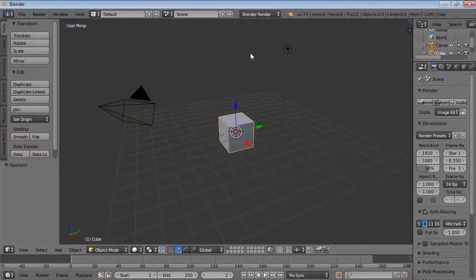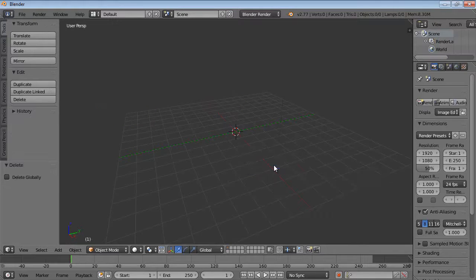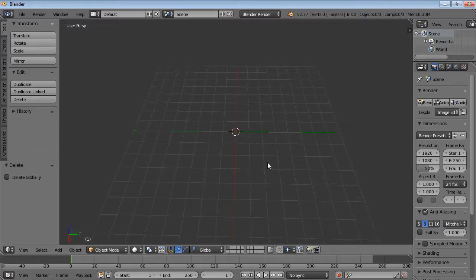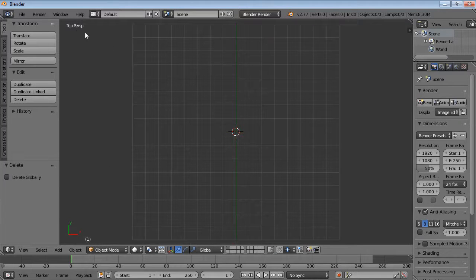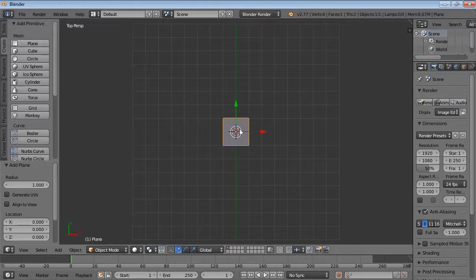So I'm going to quickly show you some things in Blender. So when we start a new file, we've got all this stuff. We press the A key, it will select everything, and the delete key, and then we can delete. Okay. So Blender isn't the 3D modeling package I'm most familiar with, but what we're doing is fairly basic. We're essentially creating a set of tubes. Okay, it's best if you've got a middle mouse button so you can move around there. What I was just showing is you can use the number pad as well.